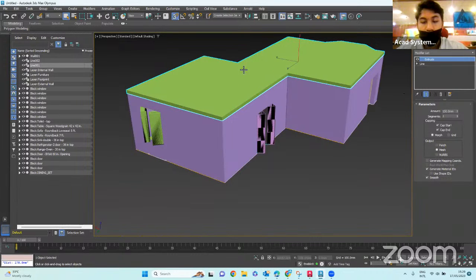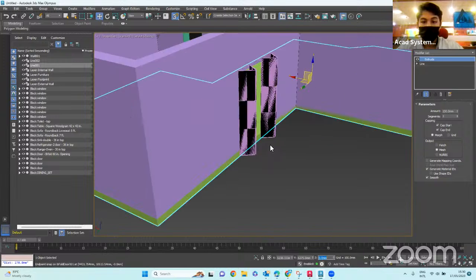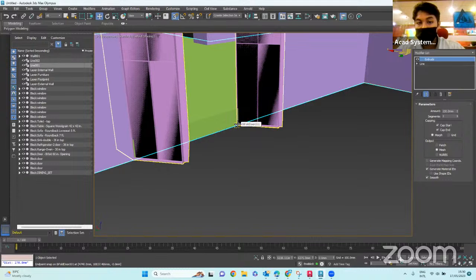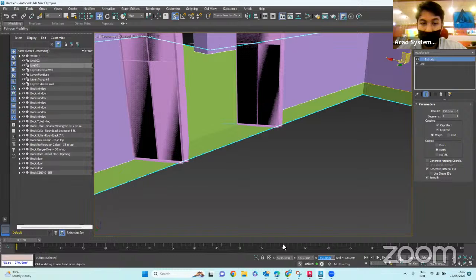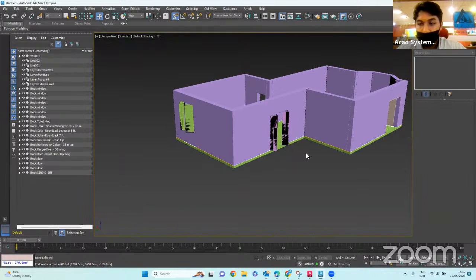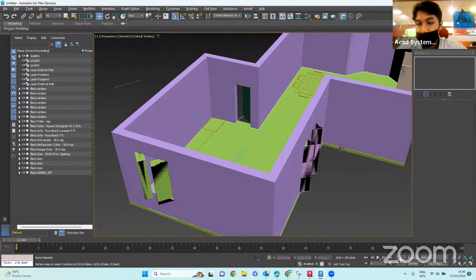So to bring it down, similar method, just click Move from your ribbon here. And then you can see the Z value here is 3000. You change this to 0 first. So that brings it down. Maybe we need an offset using the thickness of your floor. So put -150 here at the Z value. That will bring it down by 150. And then we have our floors, right?